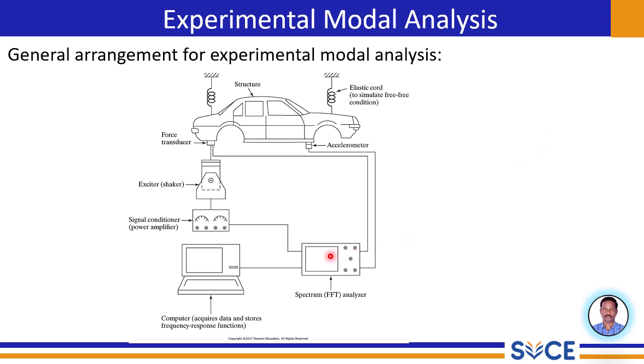Finally, we have a recording unit, that is our personal computer, generally a computer connected to the spectrum analyzer. This computer plays a crucial role in acquiring data and storing the frequency response function. It also typically runs the software that we mentioned earlier to further process the frequency response function curves to identify natural frequencies, estimate the damping ratios, and extract and visualize the mode shapes.